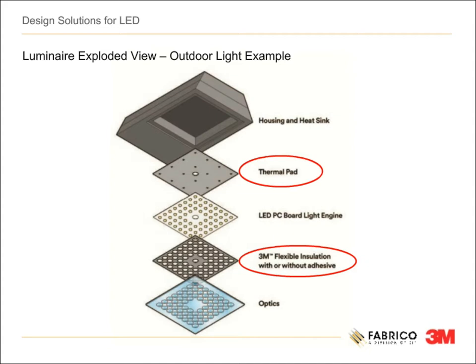3M flame barrier material is used to meet enclosure requirements between the light engine and secondary optics. This flame barrier often has transfer adhesive on one or both sides, which we will cover later. The beauty of this design is that the 5VA pattern sheet allows excellent optical transmission as compared to other designs that use either a lens with flame retardant fillers or an additional glass plate.